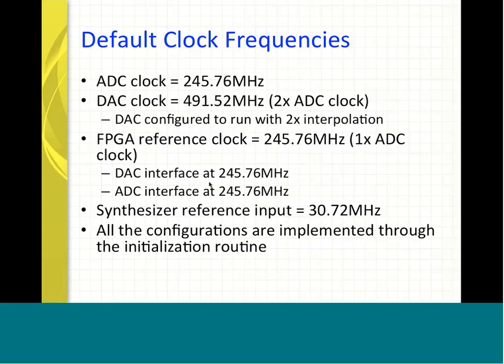As you recall, when I called out the platform configuration, there were two clock specifications: one is the reference clock, the other is the user IP clock. I specified 250 megahertz, which is a close enough approximation of 245.76 megahertz.